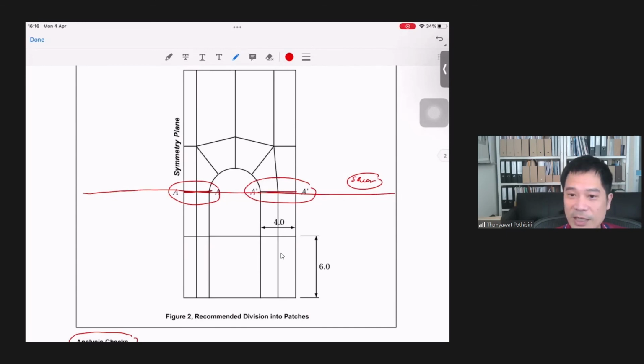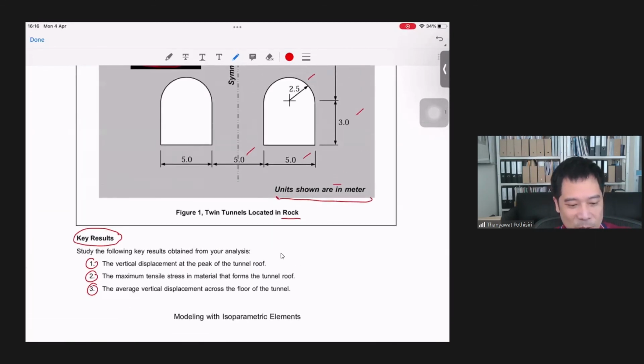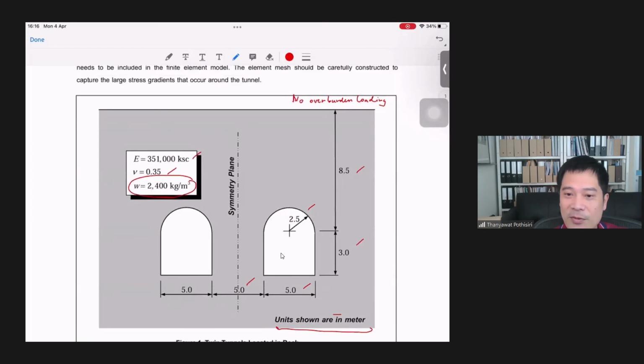The resulting shear force along these two planes should be 0, right? You should see that along these two planes, the resultant shear force should somehow cancel each other. So there should be no total shear stress. Otherwise, if you have a total shear stress but no horizontal external force, it would mean that your structure is not in equilibrium.